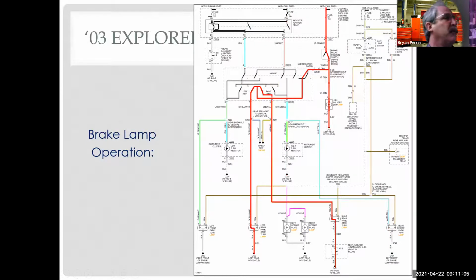I do have the problem with the brake lights, and yet with the brake lights, it can't be the brake light switch, and we've already seen the combo switch is unlikely. It can't be the left side brake light. How about the right side brake light? Do we use this for everything? Let's look.